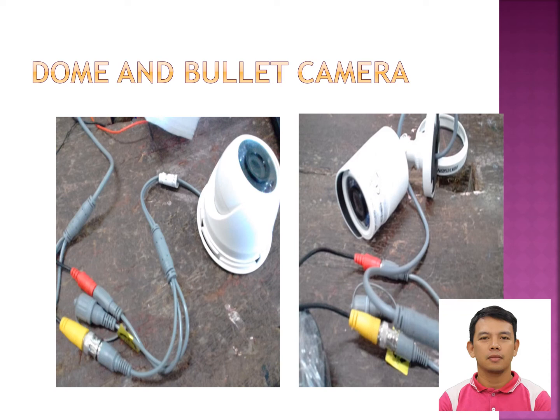This is the camera, which is the dome and the bullet camera. What I mentioned is called the BNC connector. You can buy a pre-made CCTV cable, or it is included in your CCTV set. This is the BNC connector. You connect it and then lock it.